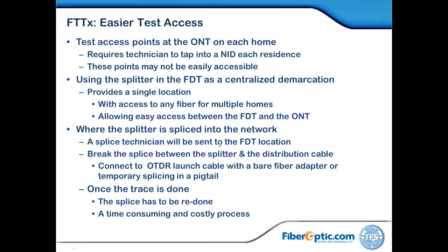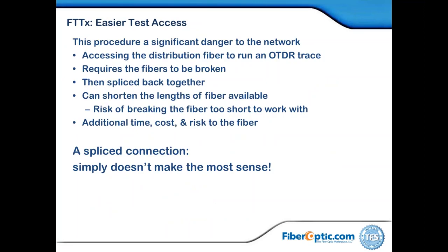Now, when things are spliced, as I mentioned just a little bit before, a high-level technician with splicing has to break it, test it, and then, as you see here, has to redo. So this is a very expensive way for the service provider to fire up subscribers, especially on a one-at-a-time basis. But it is about the connectorization. It's about easier test access. So I can access the distribution and run the OTDR as I just described. I might have to splice them back together, but plug and play, I could just plug them back in.